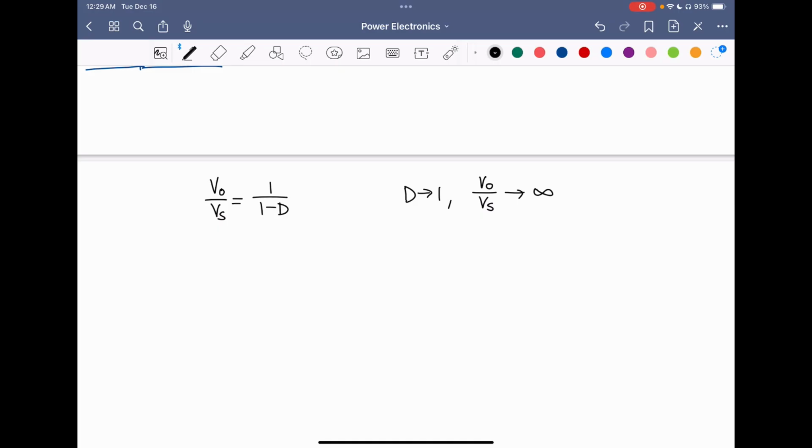This is because of a significant contributing factor being the series resistance of an inductor. Let's call it RL. So how does introducing a series resistance of the inductor affect our conversion ratio? We can now study the circuit by assuming that this RL introduces a resistive power loss in the circuit.